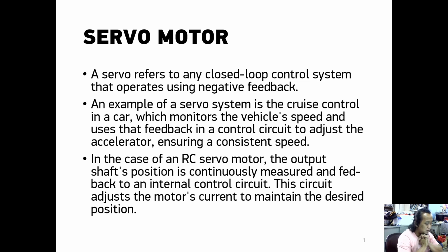I will explain about servo motor. Servo motor or servo refers to any closed-loop control system that operates using negative feedback. An example of a servo system is the cruise control in a car, which monitors the vehicle's speed and uses that feedback in a control circuit to adjust the accelerator, ensuring a consistent speed. In the case of RC servo, the output shaft position is continuously measured and fed back to an internal control circuit. The circuit adjusts the motor's current to maintain the desired position.